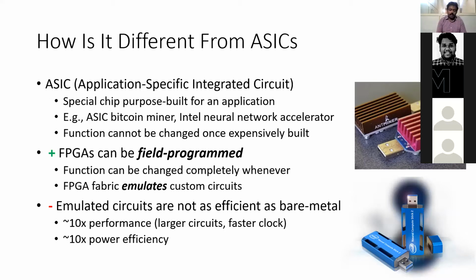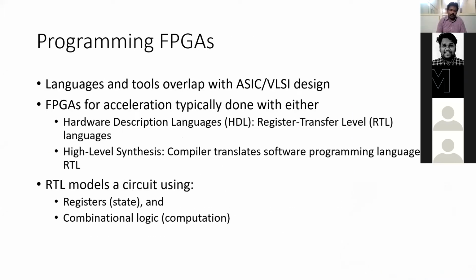So with FPGA-based designs we can reprogram it, and we can change the programming using VHDL or Verilog. That can be done according to the number of logic elements, the amount of programming, and the number of interconnects you are using. You can change everything. So that is possible. And compared to the other, ASIC is a bit faster and much more efficient because it is built for a specific application. It will have much higher speed compared to this.